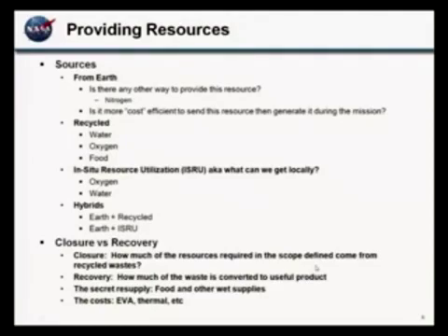They actually had a little bit of recycling going on inside there because they could take condensate from the crew and put it into the sublimator to evaporate. Now we're looking at a membrane evaporator. But the amount of energy that you can reject through phase change water is just tremendous for the amount of mass that it costs to do it. So when you're trying to be lightweight and travel, it just totally wins.